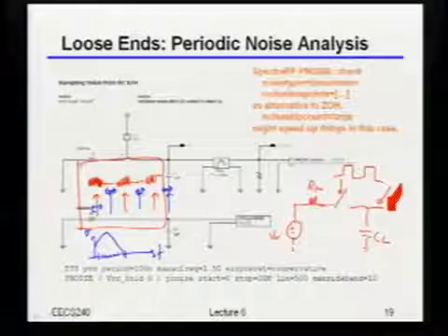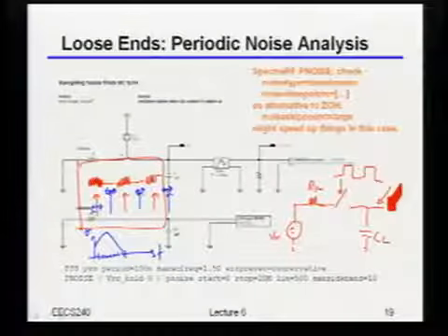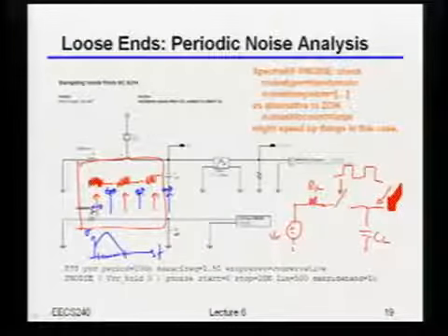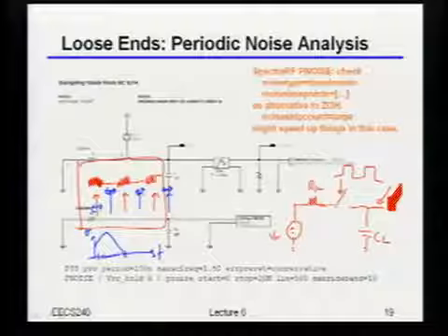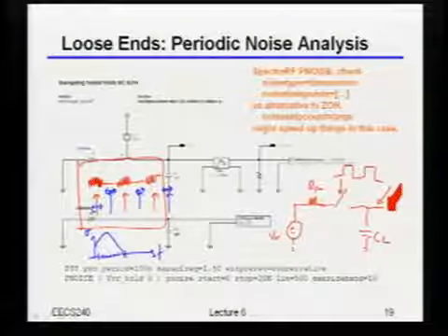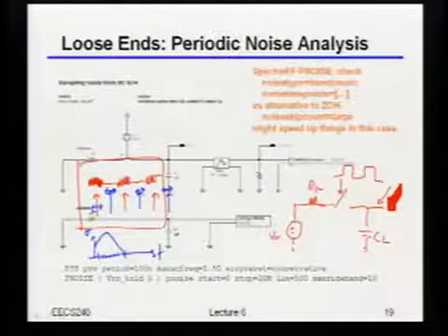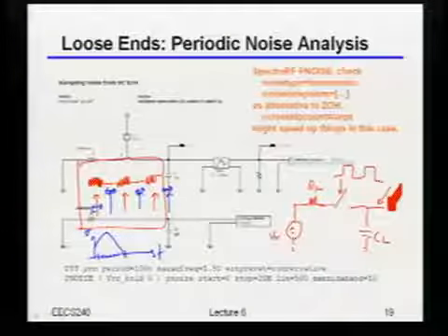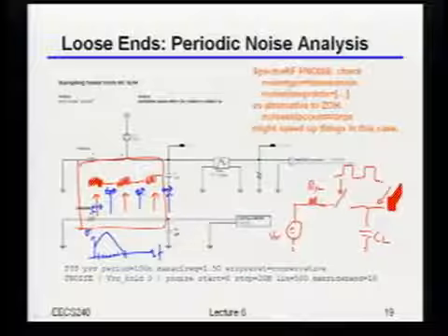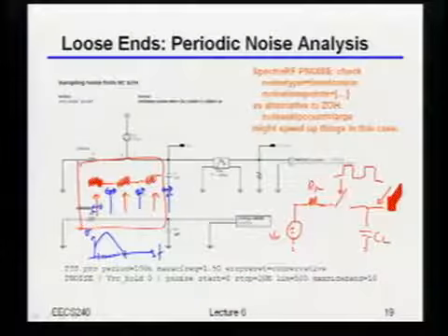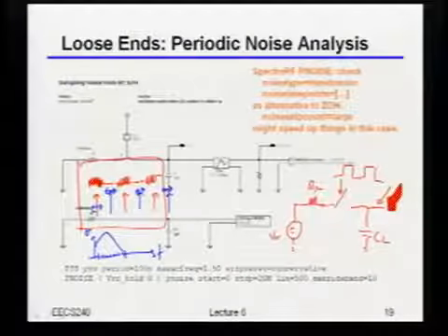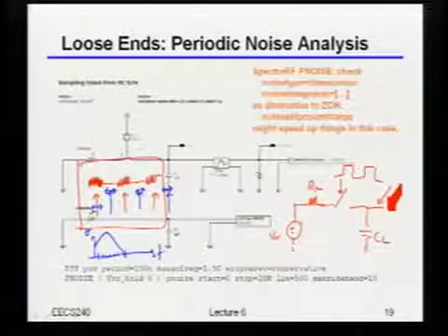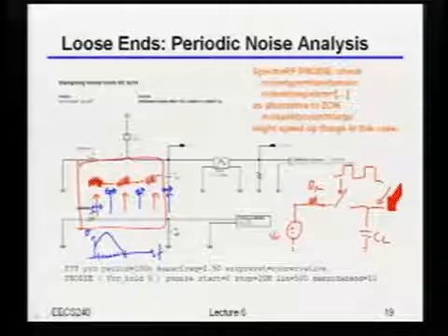So again, why do I mention this? Well, because many circuits that you deal with will have these kinds of characteristics. Particularly things like oscillators, or these sample and hold circuits. Or in fact, later we'll be talking about this quite a bit more, and you'll have lots of fun characterizing this. Things like comparators, where you trigger it with a clock, and then all of a sudden it makes a decision. They also have these very sophisticated, time-varying noise characteristics.